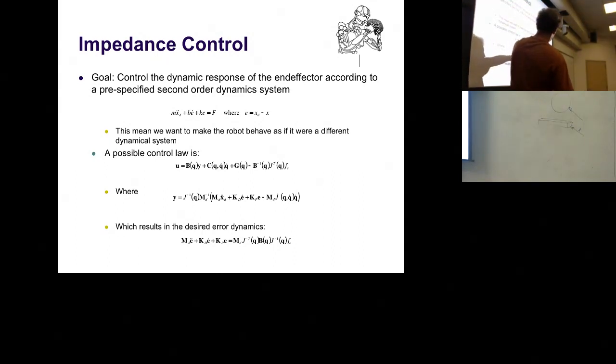This term here, as you can see, becomes a much more complicated term. You get derivatives of Jacobians in there, which are a pain. Turns out there is an analytical formula for the derivative of a Jacobian, which looks very similar to our geometric Jacobian. It's just more complicated. Most of the time, you would just take a numerical derivative of this, since it's too much of a pain to get this other thing computed. And then you can basically show the dynamics and everything, how it works out. Too complicated, not really what we're going to cover right now.